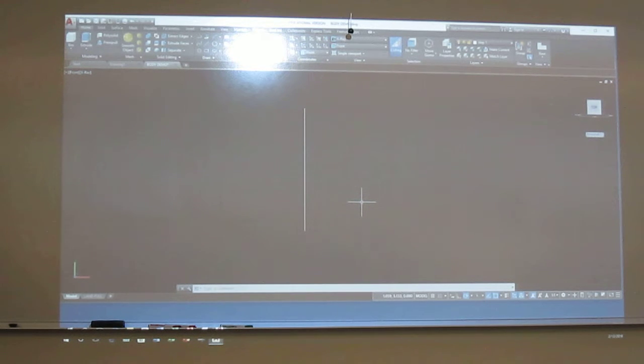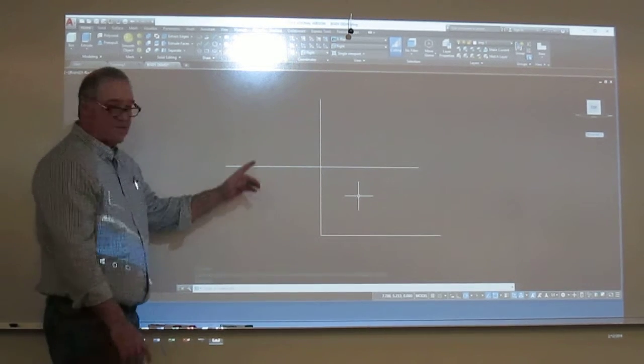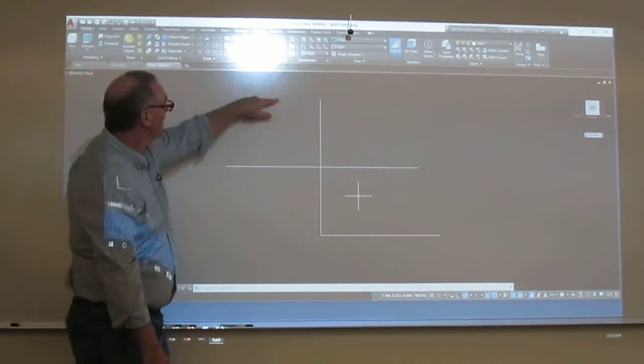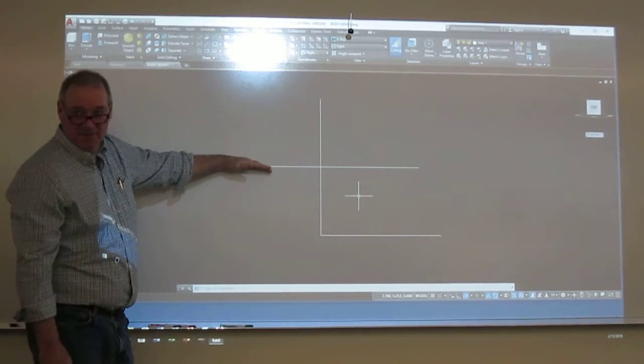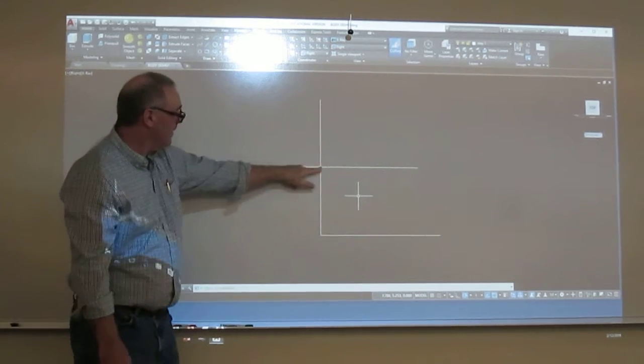Now, this is my front view, so I'm looking right into where the shaft goes. Okay. So, for me to set up my datum for where the shaft is, I had to go to the right side view, because that's where that axis is for the shaft that goes in that hole. So, if you would go to the right side view now. Now, to create this datum, all I did here, folks, was I came from the top, I drew a line straight out, and I offset it the distance down. It's 1 1/8 inches if my memory serves me right. And that gave me this line.